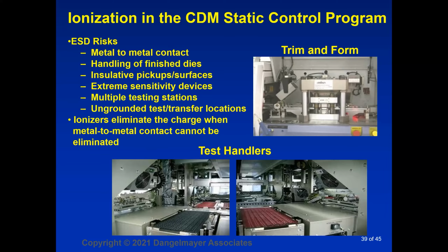So for instance, in a test handler, if your product is charged, when you put it into the socket, you're going to have voltages induced on the pins of the device. And when they touch the metal pins of the socket, you have ESD. The socket itself is an insulator. It has to be to separate the contact pins. The package of the part is an insulator.